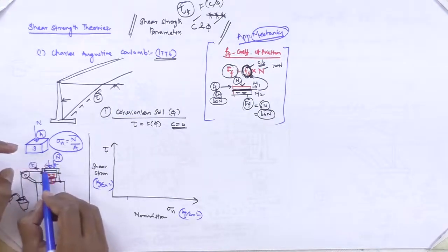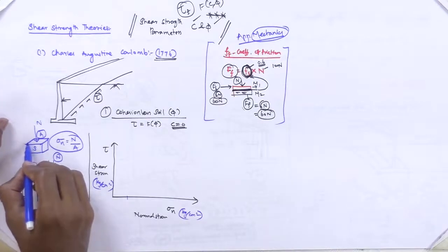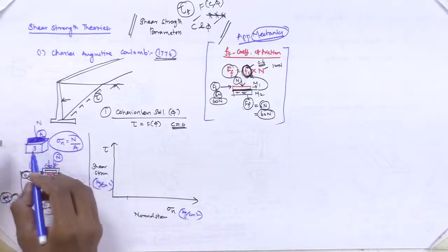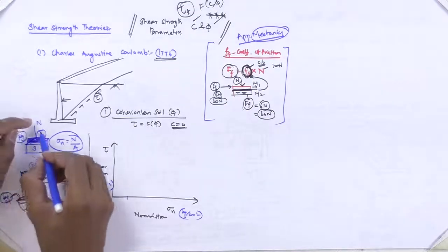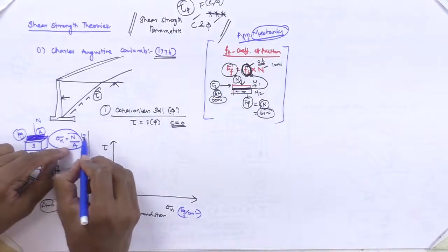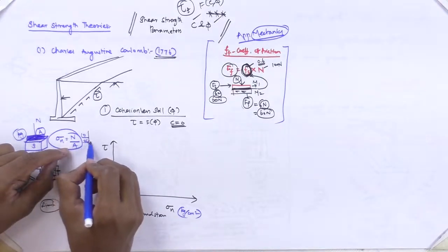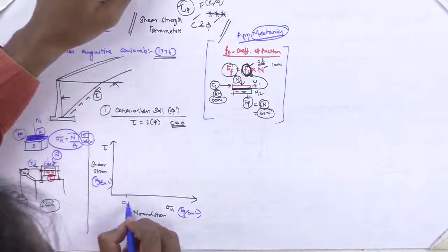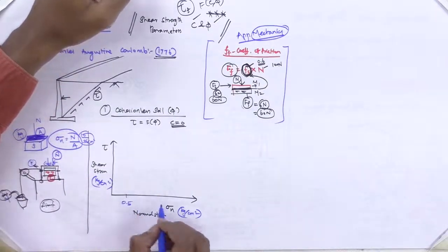So this is where he is going to place some measured load. By the way, this is measured in terms of kg. So this is the normal load, say 10 kg applied for the area of 36 centimeter square. Whatever it may be, here it is considered as 0.5 kg per cm square in the first trial.